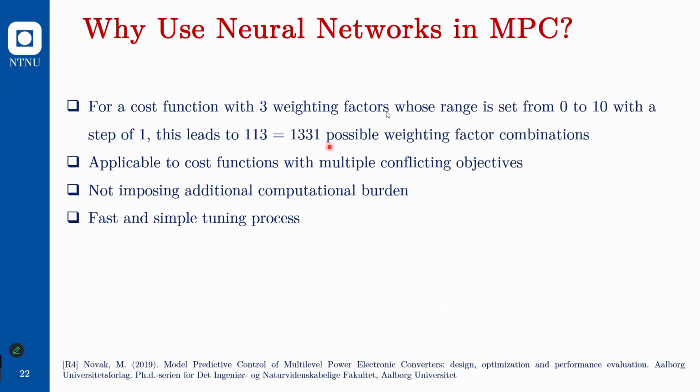And we are also not going to use another optimization algorithm to predict these switching weighting factors, because MPC itself is already an optimization process, and you would be adding another optimization on top of that. So the controller will go mad. To avoid that, you can use a neural network, because it is just a combination of certain mathematical equations. I mean, just multiplying the weight values and adding bias values. We'll see that. So that is one way of using the neural network for MPC to address its limitations.